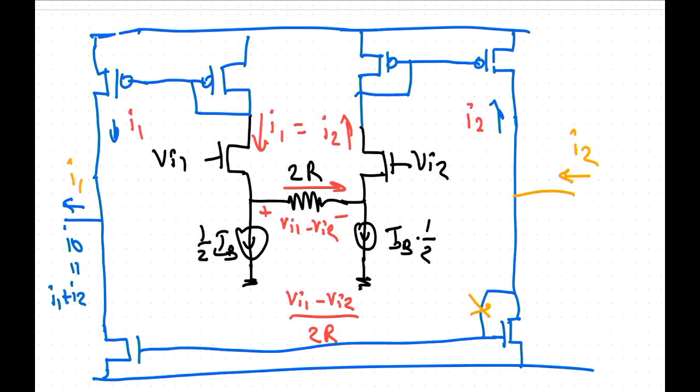So you can take these two outputs here, just as you want, if you implement a folded cascode amplifier. You have a differential pair with two outputs you stick into the folded cascode structure. You just do the same. The only difference is that you have linearized the diff pair. That's the only difference. It just seems to look different.